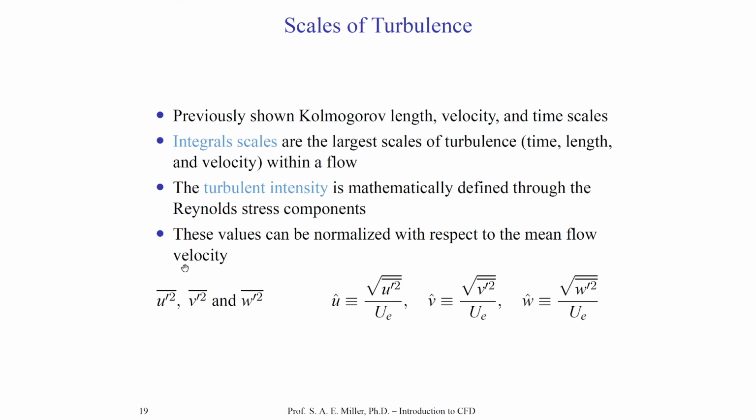So through this idea and process of the RMS value, root mean square, we can rewrite our velocity statistics in this way, as u hat will be the RMS of the velocity divided by, say, the average velocity magnitude. V and w will likely be the same. There'll be v prime and w prime instead of u prime. And so now we have 3 RMS components which are normalized by the mean values. Let's keep these 3 equations in mind.